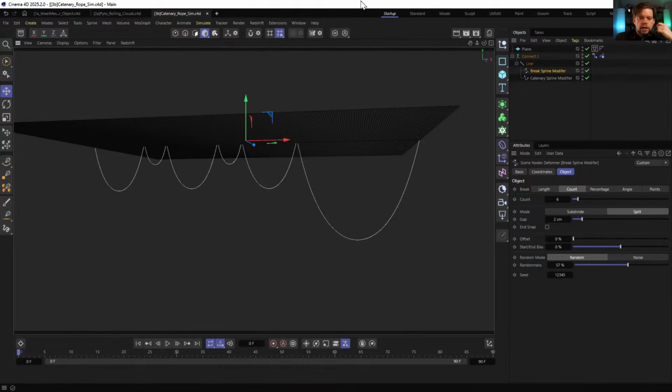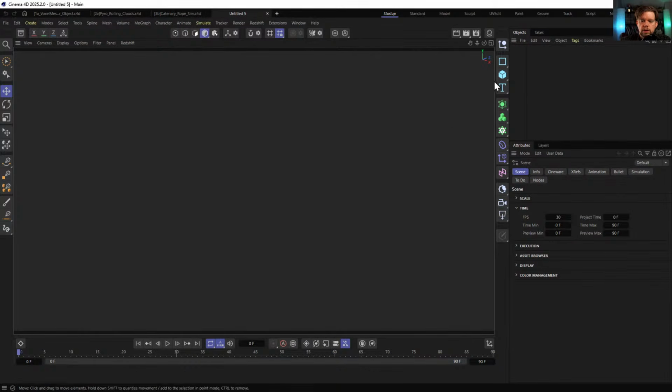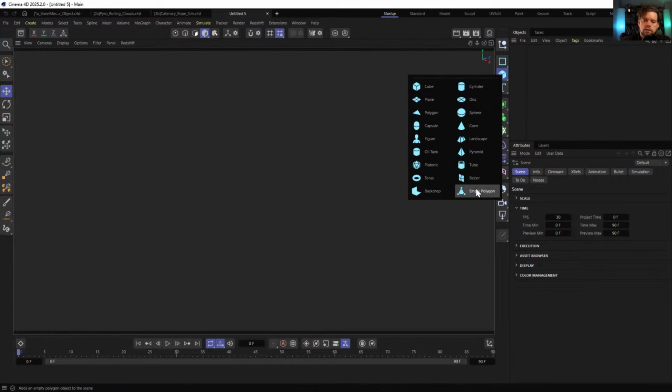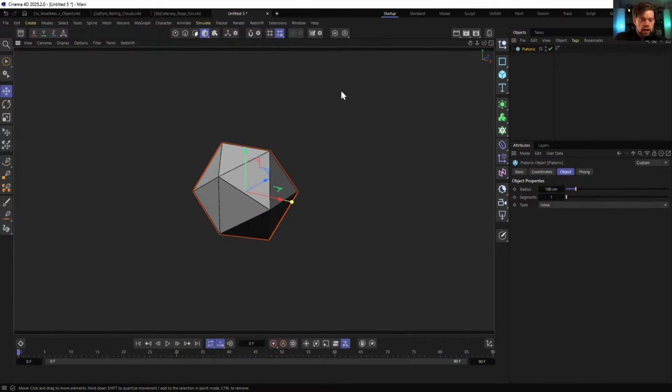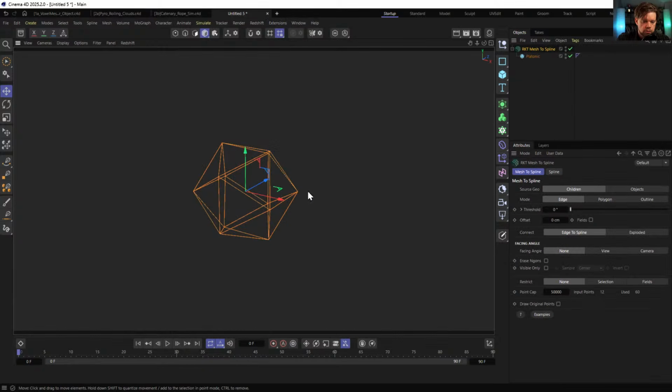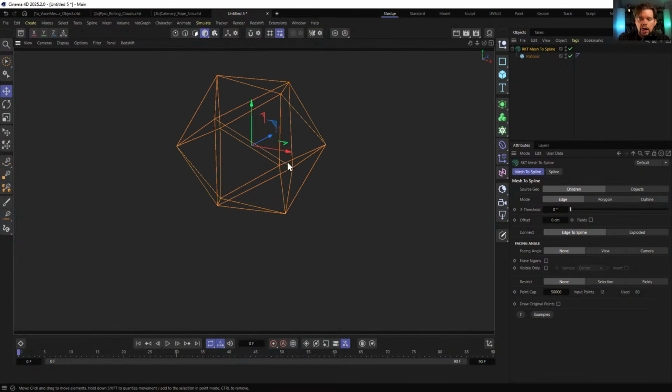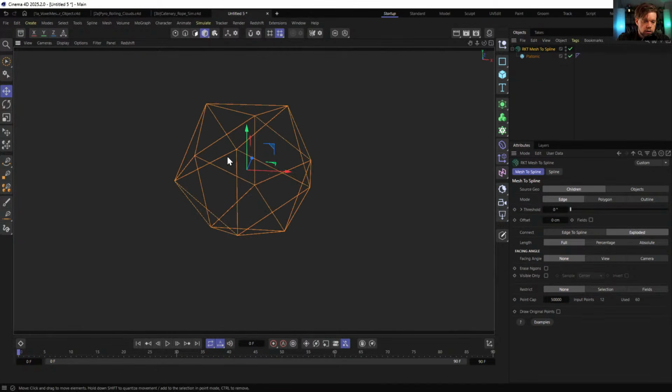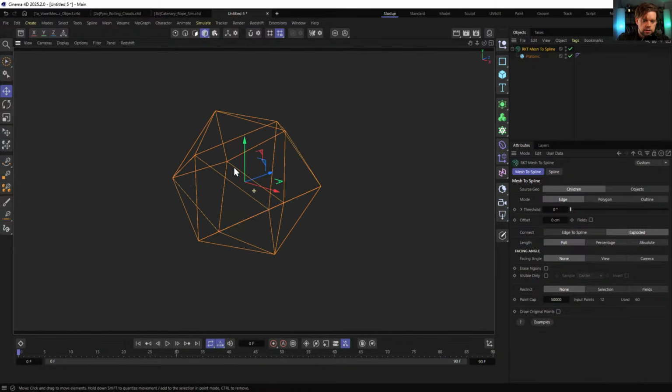The catenary spline, while we're playing with the catenary spline, I'll just show off another thing it can do that I think is pretty cool. I'll open up a new scene file, and what shape do I want? It's actually the one I typically do, so I guess I'll use it again. So we'll make one of these, and we could say edge the spline, but I'm just going to use my tool, mesh the spline, so I can convert those parametrically. And I can even say exploded. So now each of these is its own little line segment.